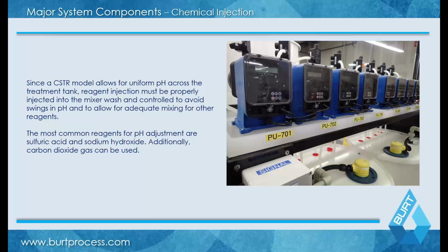These chemicals are obviously hazardous, so they do need to be stored and contained properly. This typically involves having segregated 110% double containment of each chemical individually. You also need to segregate the metering pumps from each other, and you need to have double contained lines for these, because this is where you're really going to be handling the highest level of chemistry in your system.